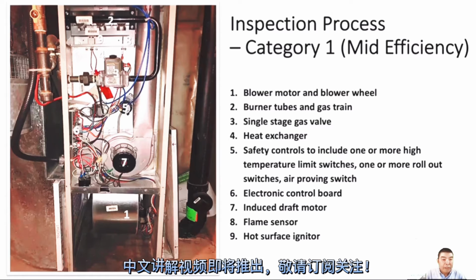If the pressure switch doesn't feel the inducer motor running, or for example the pressure switch has failed, then even if the inducer motor is running okay, there is still no signal to the control board. In that case, the furnace gets the information that it cannot run the heat.